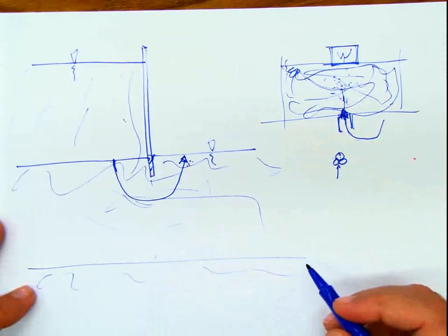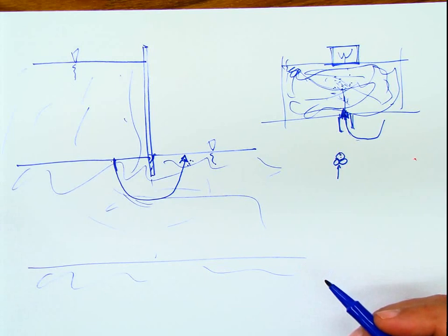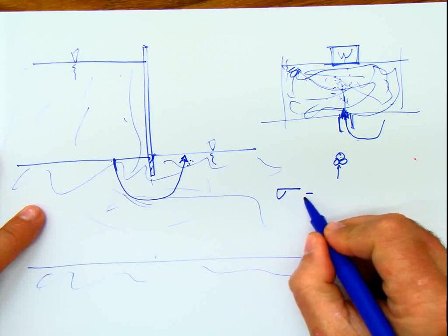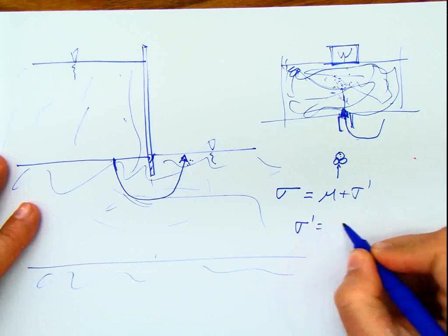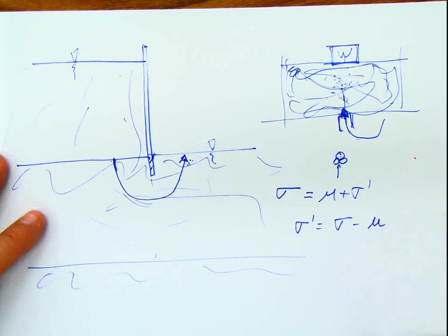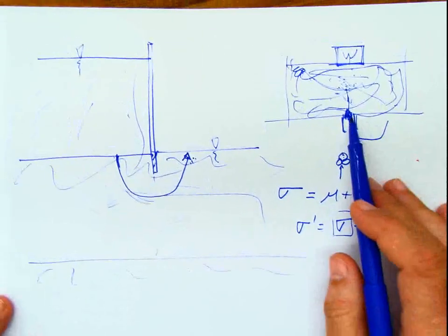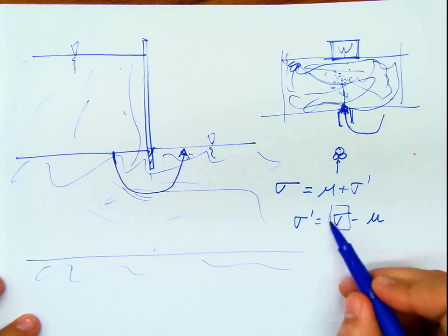And if that is happening, it's because somehow the effective stress is affected. Now, the total stress is sigma equals U plus effective stress, so the effective stress is sigma minus U. The total stress is not going to be affected by a flow of water, because the total stress, if you remember what I told you, is just the weight acting on top of the point that I'm in, the section or the area that we are referring to.